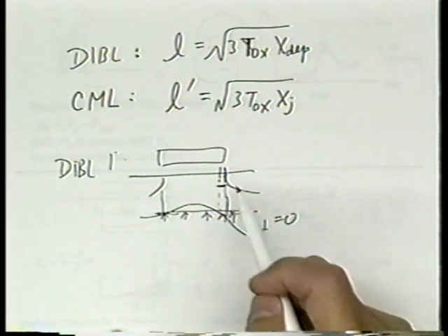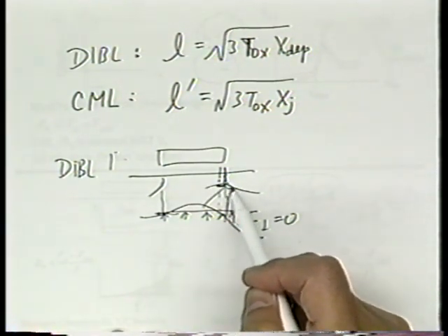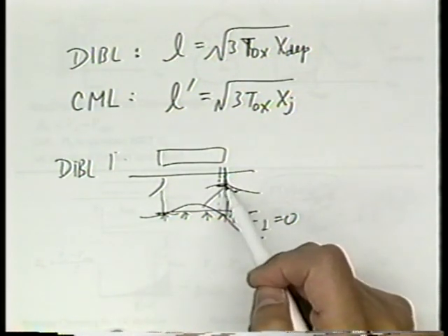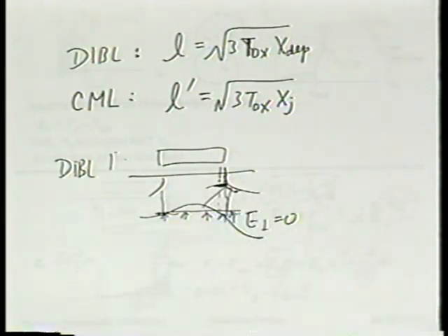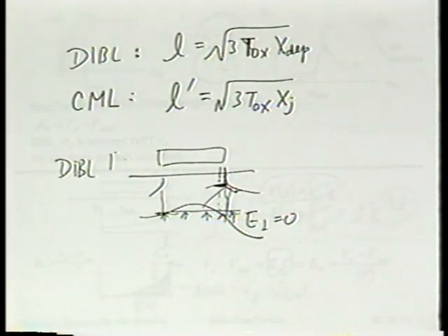The reason is that at the junction depth, we know there are many electric field lines because the corner is sharp, right? One of these field lines is probably pretty flat in this few hundred angstrom distance. And that field line can be used as the bottom boundary of the Gauss box. You see what I'm saying?